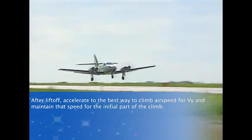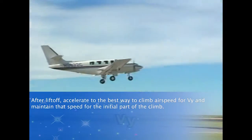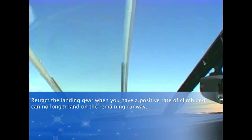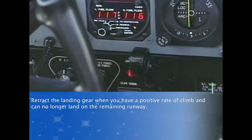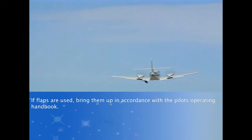After liftoff, accelerate to the best rate of climb airspeed, or VY, and maintain that speed for the initial part of the climb. Retract the landing gear when you have a positive rate of climb and can no longer land on the remaining runway. If flaps are used, bring them up in accordance with the pilot's operating handbook.